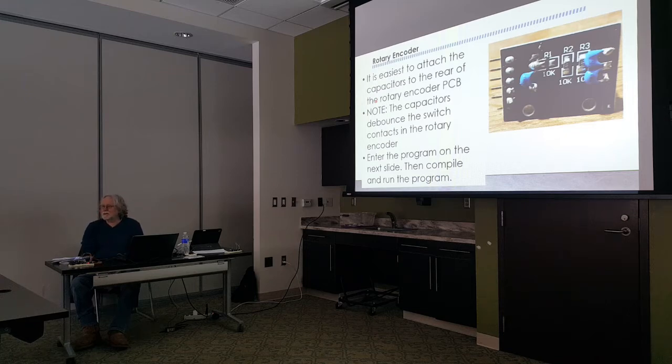And the interrupts happen real quick. So you go in and out of the interrupt 2 or 3 times each time you click it, and all of a sudden you're saying, what the heck is going on? That's what it is. So you throw a capacitor on there, and most of the time it takes care of it. You don't have to do it in software. If you're running out of space on your circuit board, you do it in software.